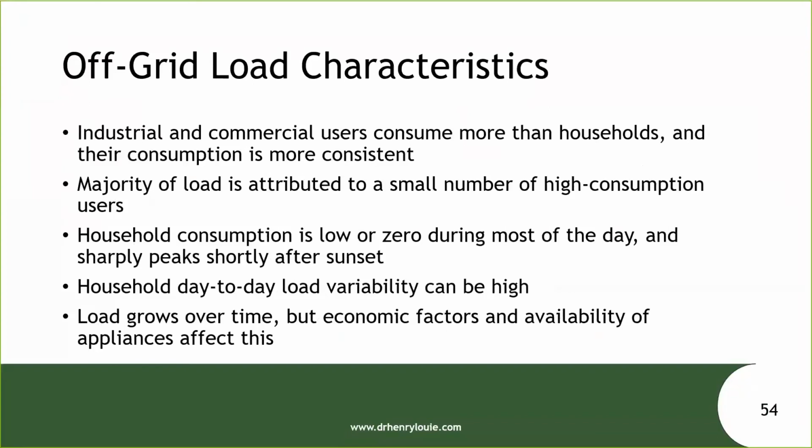Here's a few tips just to make your system a little more financially stable: look for industrial or commercial users. They're the ones that are going to have more consistent consumption, and they'll likely be able to pay for their connection. Almost universally, the majority of the consumption is going to be attributed to a small number of users. Most users are going to use 0 or a very, very small amount of energy per month, a few watt hours even. But a few are going to use a lot. And so if you want your system to be financially sustainable, you need to find those users that do consume a lot.